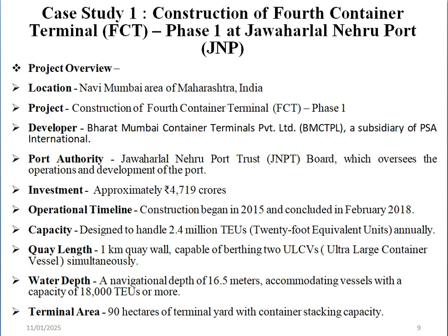Quay length: 1 kilometer quay wall capable of berthing 2 ULCVs, ultra large container vessels, simultaneously. Water depth: a navigational depth of 16.5 meters, accommodating vessels with a capacity of 18,000 TEUs or more. Terminal area: 90 hectares of terminal yard with container stacking capacity.